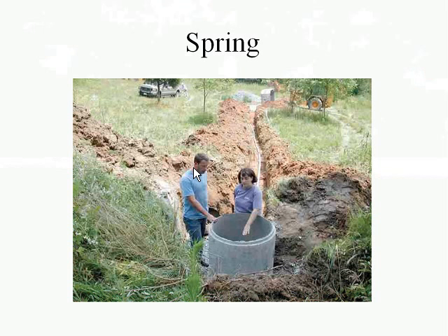Springs. One of the sources that we have a standard for is spring development, where basically we're going to capture water from either a high water table system, where we're going to do some subsurface drainage and drain into a well, or we're going to capture some water off of the slope. How to do that is all covered in that standard for spring development.